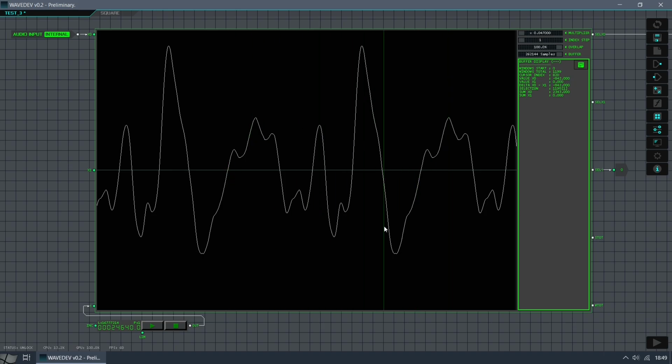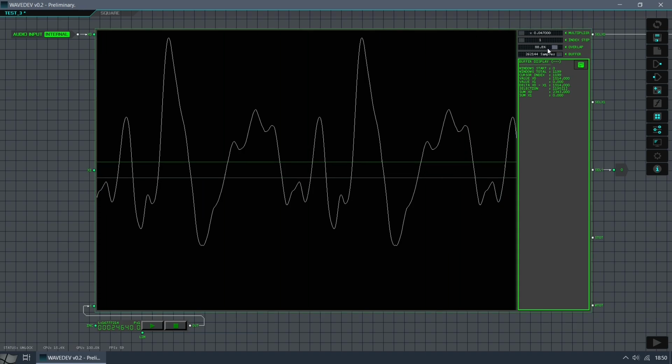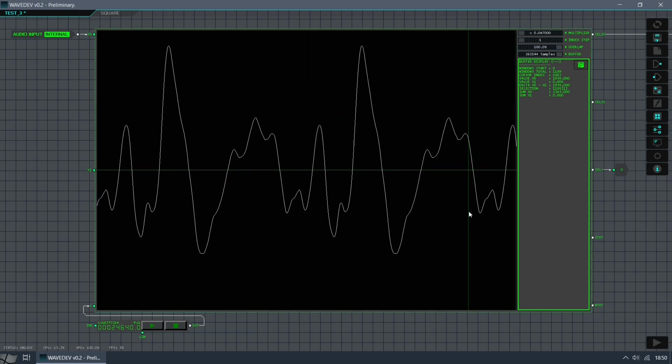Here I have captured some samples with the same buffer display from the analysis of the amplifiers. Unlike an oscilloscope, which is not very stable to sync with composite signals, the buffer shows static data. So we can work on a specific segment of the signal that we keep unchanged. This instrument has a buffer index selector. So we can select the place within the buffer to store the sample that enters through these nodes. We have two buffers here, so we can use them to compare two signals. To record continuous samples, you must use an external counter like this one, or another similar source.